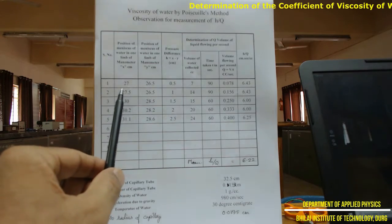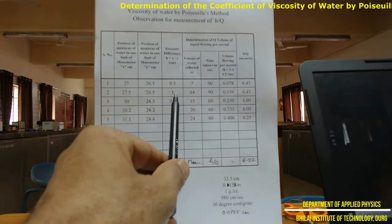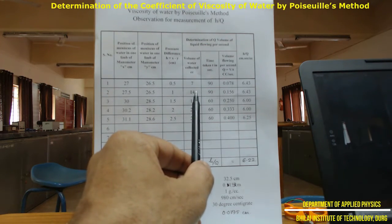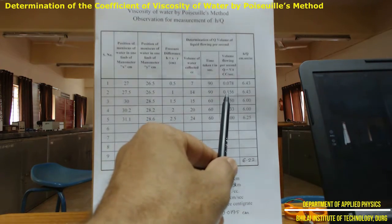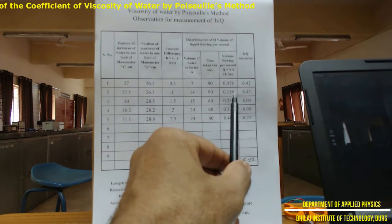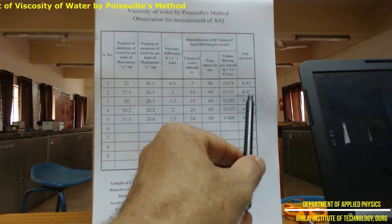Similarly, in the second reading, we raised it to 27.5. It was still 26.5, so the difference between these two is equal to 1 centimeter. Volume collected was 14 ml or 14 cc in 90 seconds. So 14 divided by 90 gives us 0.156 cubic centimeter per second, the volume collected per unit time. Now dividing 1 by 0.156, we get 6.43, again h by q.